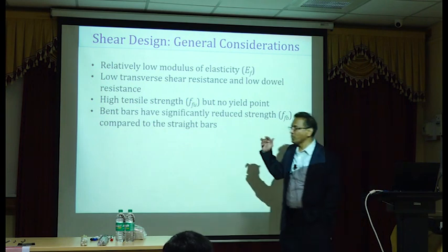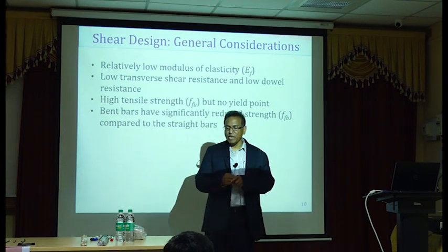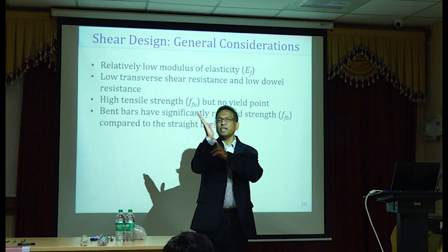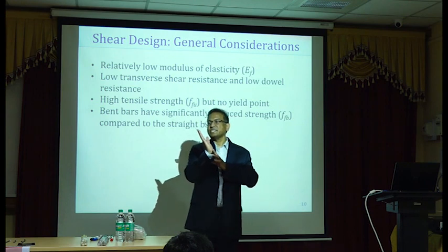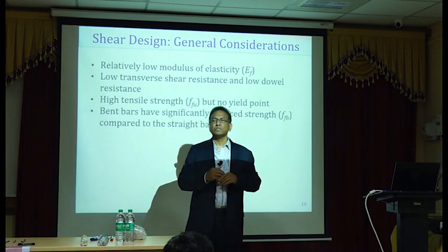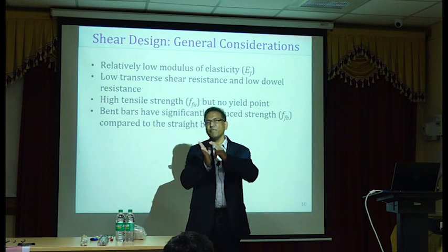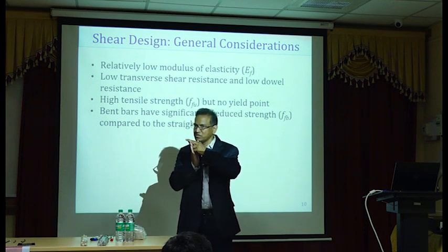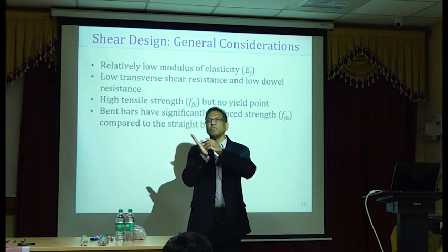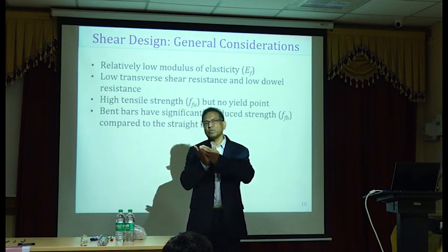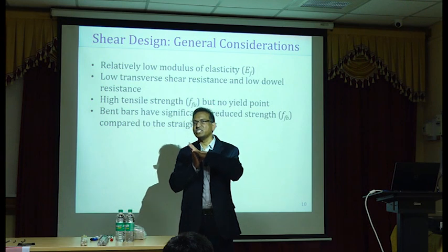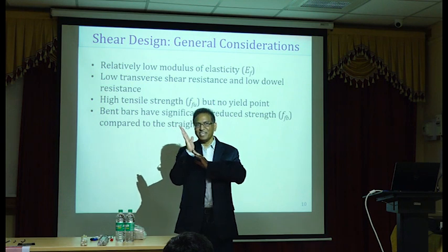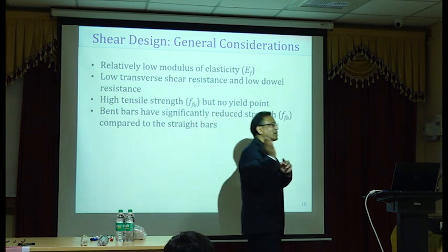When I say it's a problem, what I mean is, if you have a linear stress strain curve and the stress at failure is about 1000 MPa, we will never ever design with a 1000 MPa limit. We'll always design maybe at 1/3, or maybe 300 or 400 MPa. So the advantage of the high strength is also lost because of the linear stress strain curve. Okay, so that's what I mean.